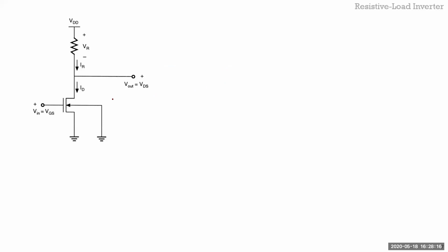Okay, so if you look at the resistively loaded NMOS inverter, here the load is actually a resistor. I've already gone through that in the first slide, but quickly go through it. The way this works is when your input is 0 or less than the threshold voltage, this doesn't have any channel, this one is off. Usually there's a load capacitor here.